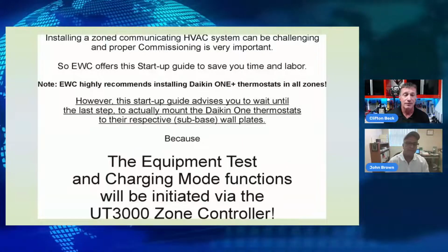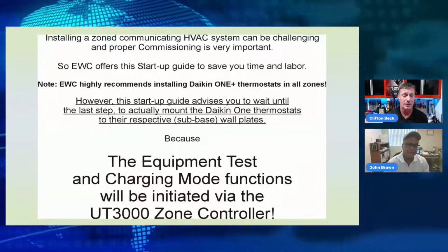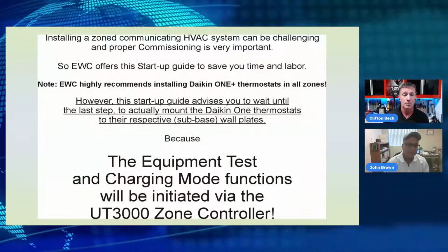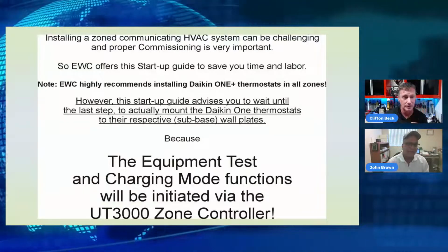Yeah, I always told guys if they have an issue with the outdoor unit not pulling up onto the network and they're reusing wire, find the closest window or door, grab you a spool of fresh conductor wire, throw it outside, and run you a fresh new line.